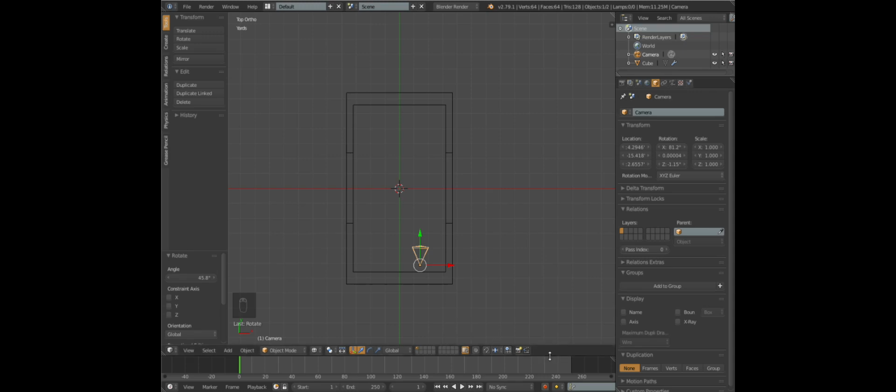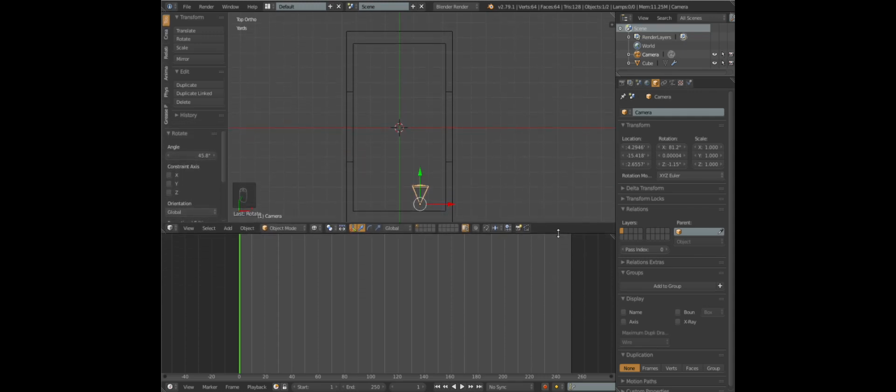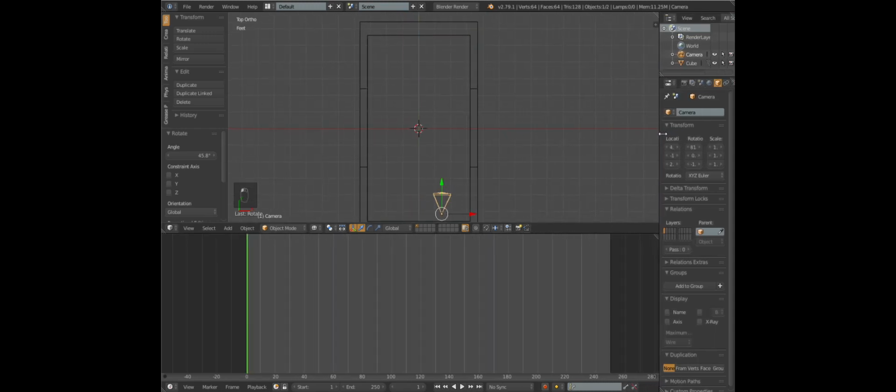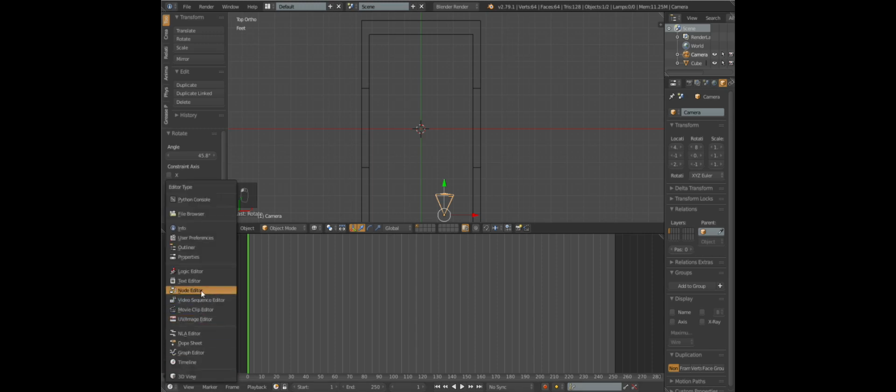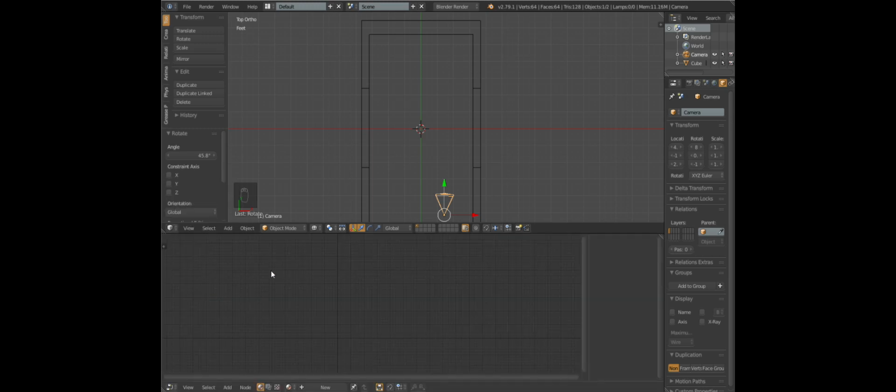Alright, so in Blender, let's go ahead and set up our interface so that we can work a little more efficiently. Let's slide this menu back over so that it's kind of small. Lots of room up here, and then the lower part will switch to be the node editor, and it typically comes with that menu out, so that's just N to hide that. And then down here, the students will hopefully remember that we don't have all the options that we want, so we have to go up here to change the render engine to Cycles, and Cycles will help us get a little more realistic